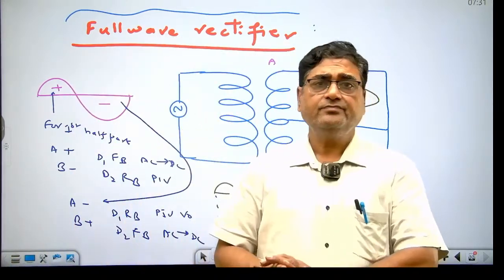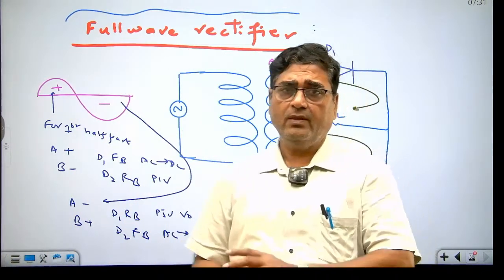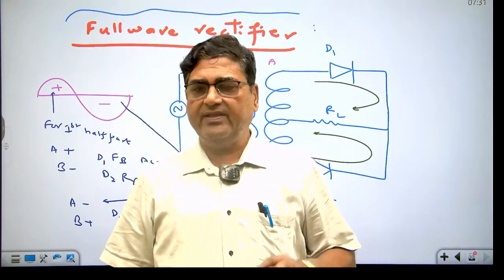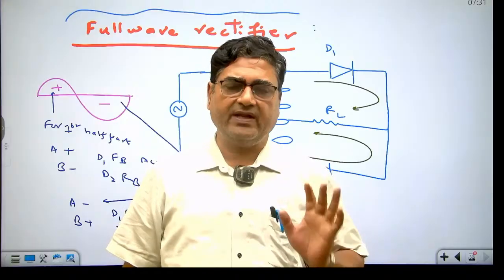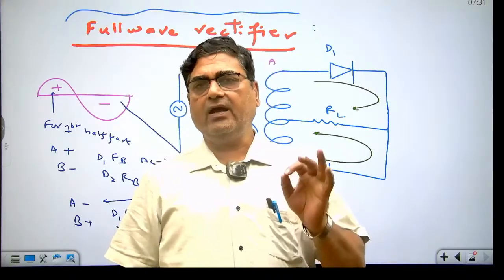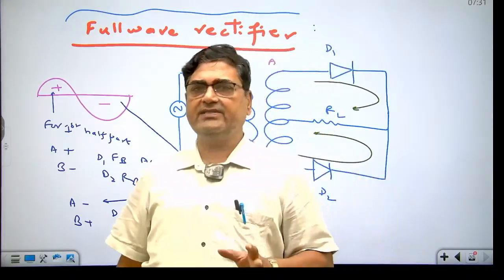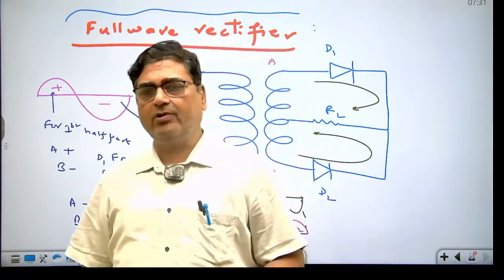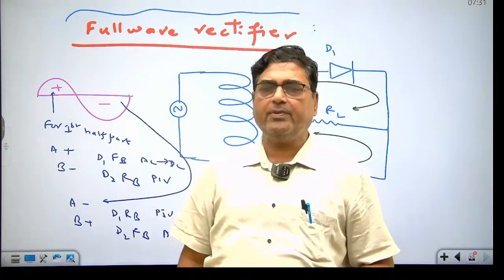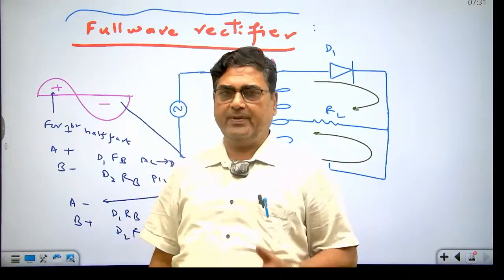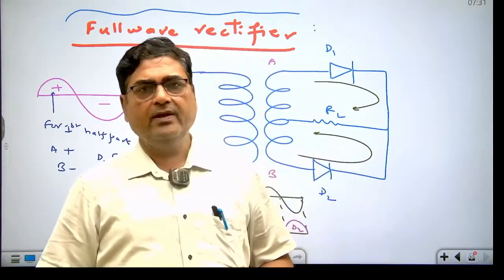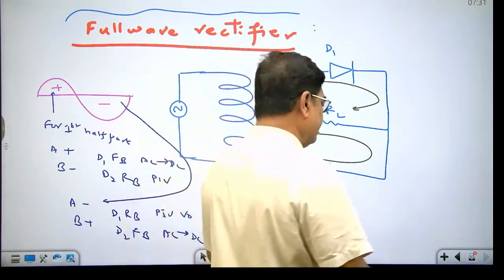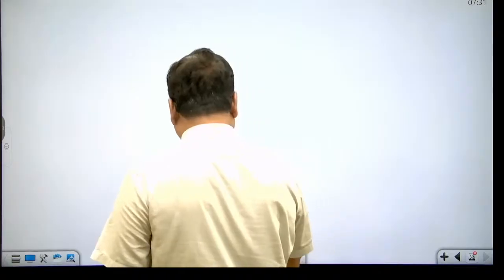So dear student, whether you use a half wave rectifier or a full wave rectifier, in the output of the rectifier you will get pulsating DC, meaning AC will remain mixed in the DC. The presence of AC in the output of the rectifier, as I told you earlier, is called impurity, that is ripple, okay? If you want to remove ripple, you have to use filters made up of inductor or capacitor, LC. How does the LC filter work? Look at the working principle of filter.